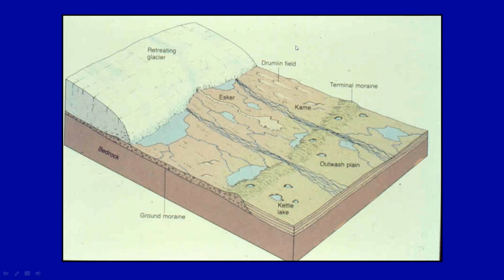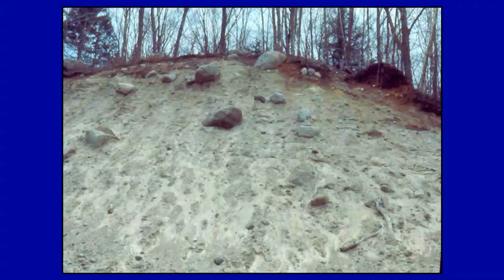Cartoon here showing exactly what's going on. If you'll notice clearly, here was a stream beneath the glacial ice depositing an esker. Drumlins, and I will explain this in a little bit. We have a terminal moraine. I indicated that we advance forward, pushing material. This would be glacial till, and here is an outwash plain, something that again we look forward to finding because the potential for a high yielding well exists in that type of deposition.